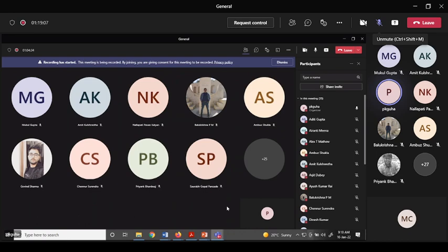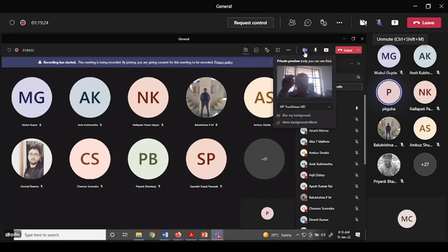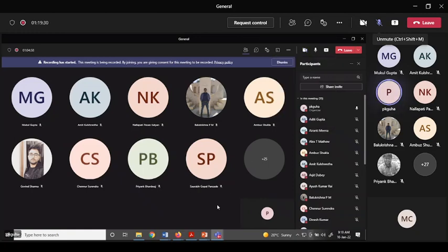What we do is ask the fabrication lab, I want to fabricate my device, my circuits, using, quote unquote, a particular process node. Probably you have heard of a 180 nanometer process or 330 nanometer process. These are specific process nodes, or a 1 micrometer process. What I mean is that the minimum length of the MOSFET supported by that process is 1 micrometer.